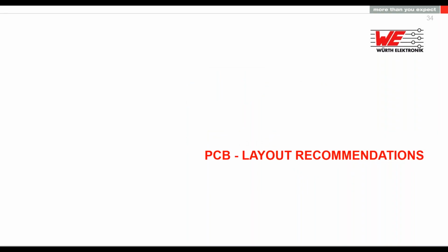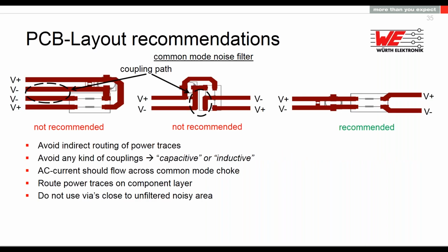Layout recommendation. You can sometimes do crazy things with layout. I can tell you from my experience, a customer had to pass an EMC test. We were together in an EMC lab, and we soldered by air, using an air PCB, just wires. We soldered a common mode choke and 2 capacitors, and he passed the EMC test. Finally, his homework was to go home, put that on the board, and get certified.